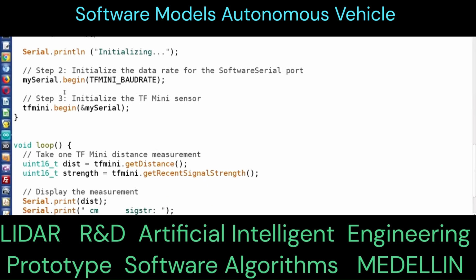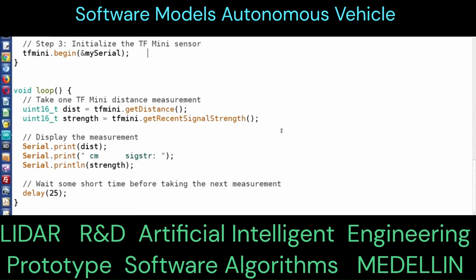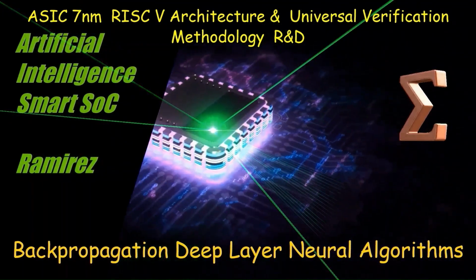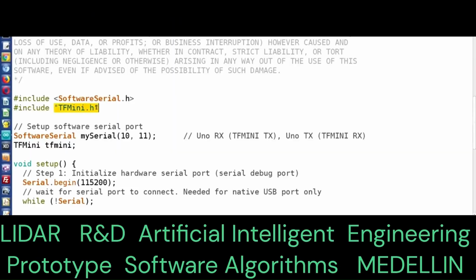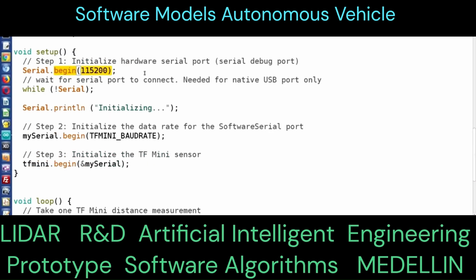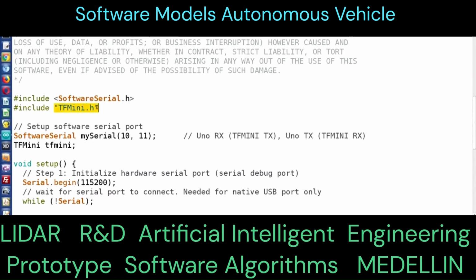The software algorithm methodology is described in this project as I have illustrated in this video. So, first include the SoftwareSerial.h file. Then include the TFMini.h file.